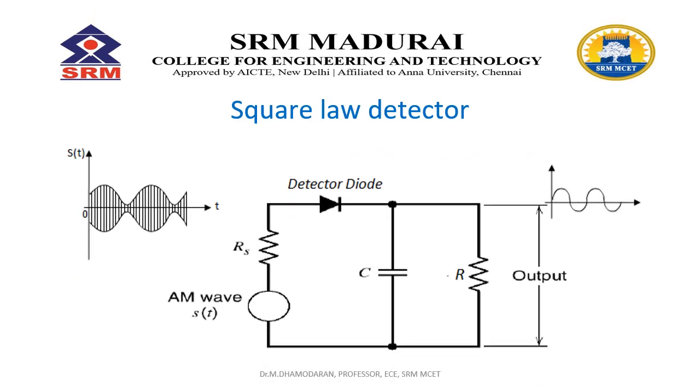Now we can see the square law detector. Here also we are using one diode, called the detector diode. The AM is the input signal, and it goes through this resistance. After that, the detector diode converts the high frequency to low frequency. We have one RC circuit, the capacitance and resistance circuit. The input is a double sideband AM signal, but at the output we get only the message, the envelope. This is the basic idea of the square law detector.